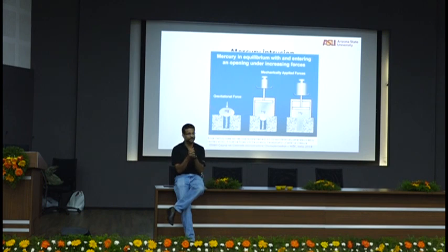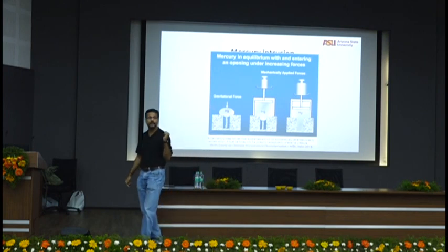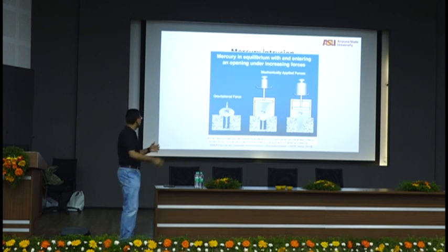If compression causes failure, none of us would be living, because this building is exerting more than the uniaxial compressive capacity of the substrata that this is sitting on. We should be sinking to some underworld already. We should have sunk already. Because it's all triaxially confined, you will have no compressive failure. That's exactly the principle that you have in the mercury intrusion process. So you have triaxial compression.